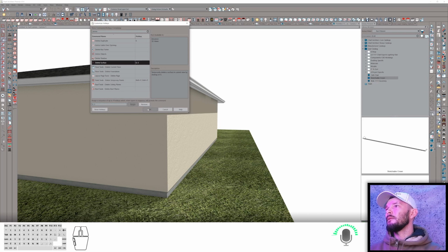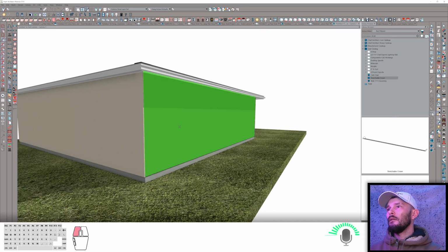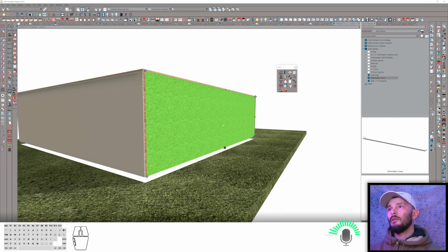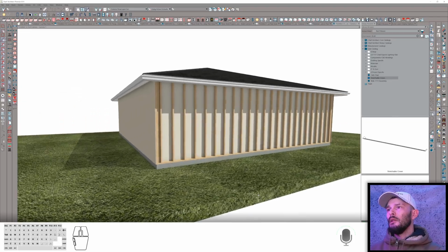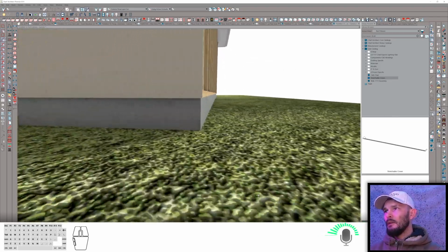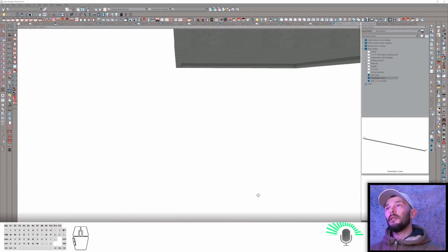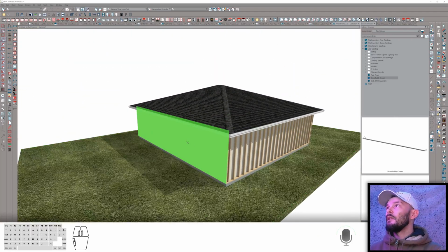See if it conflicts with something. It doesn't. So now we got a delete surface tool. There we go. Oh, we would have had to build framing first. Show it in this view. Sure, why not? Now we can use my delete surface tool. Kind of pick it up. Yeah, so we can see framing is aligned on that foundation wall, and that footing is aligned with that outside of the footing. Easy, easy.